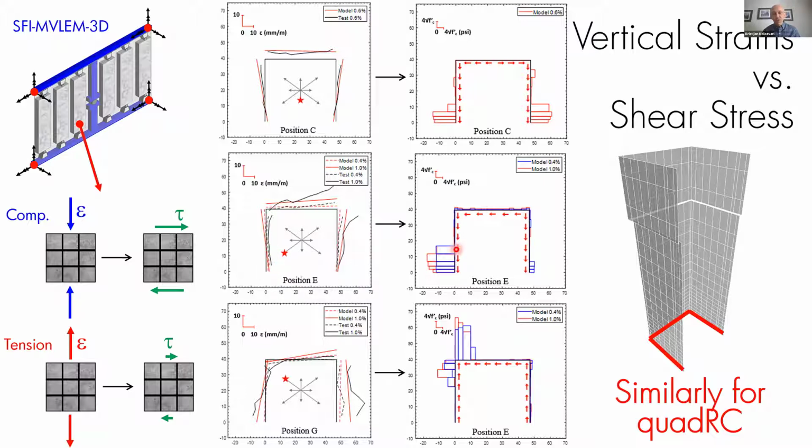All the shear stresses are also concentrated here and here. And same conclusion in this direction. All the shear stresses are really concentrated at this boundary because that's the boundary that is in compression. Everything else is in tension in terms of the cross section.